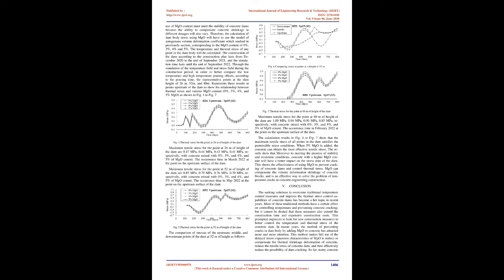The thermal parameters of concrete mainly refer to the thermal conductivity, the surface heat exchange coefficient between the environment and the concrete, and the autogenous volume deformation. Moreover, attention should be paid to increasing concrete temperature, elastic modulus, and creep deformation. These parameters depend on the age and temperature of concrete.